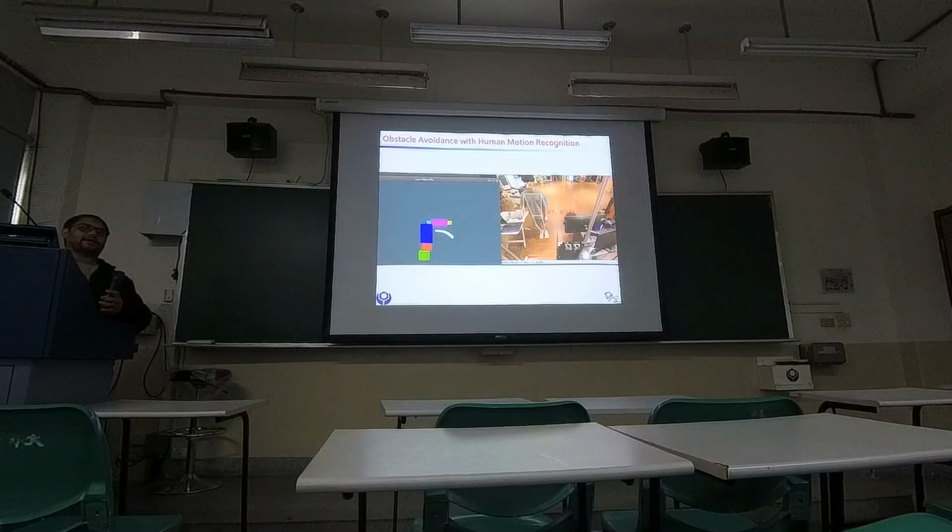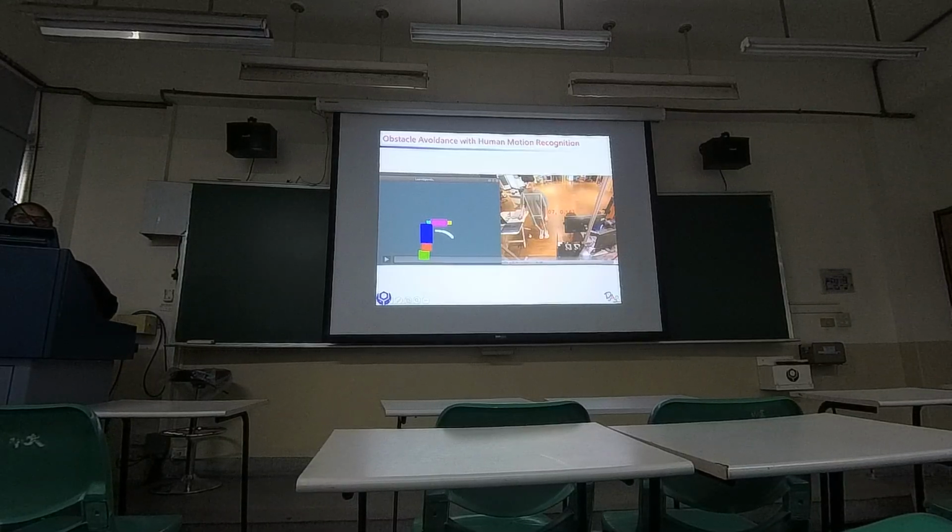But you can see how we can find this. What we have done in our work is we have taken a number of points as a sphere, because we have used a sphere representation in our trajectory planning. We have used certain points incorporated as a sphere, and the trajectory planning works using the sphere, not individual joints. Like 2 or 3 joints can be plugged together to make one sphere.